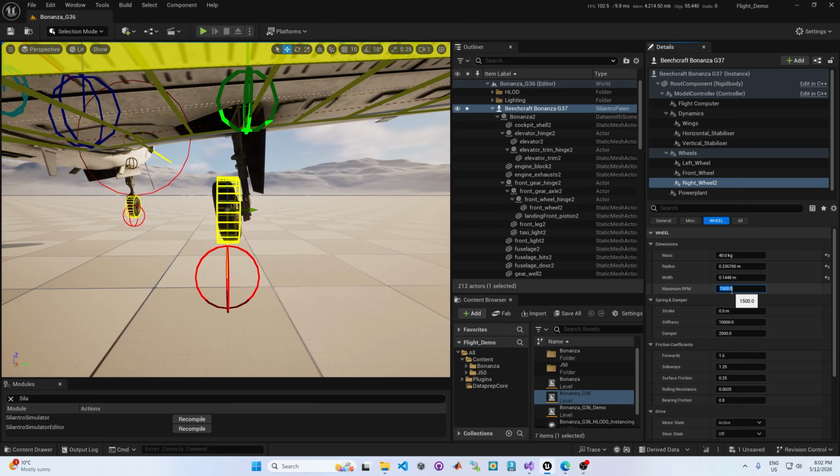Not stop, go to zero. It's going to saturate at this 1500 RPM. So this is the maximum rotational speed of the wheel to keep it from going off to infinity and actually applying extra forces to the aircraft, because the wheel applies ground forces and moment.